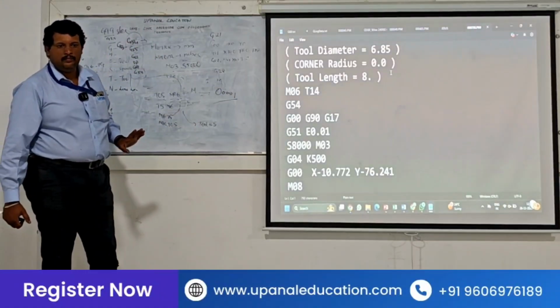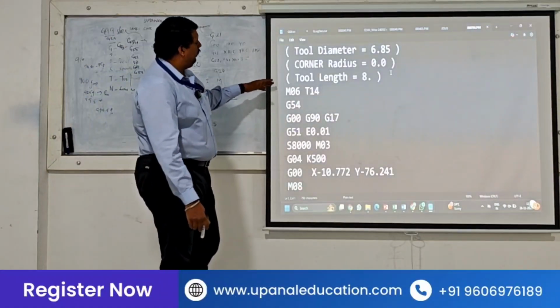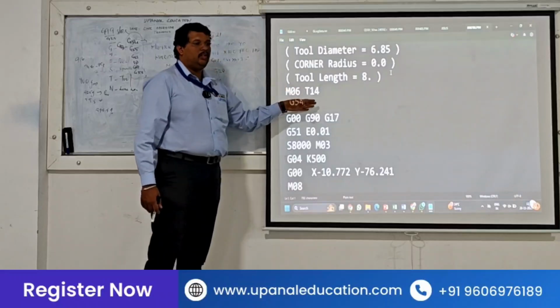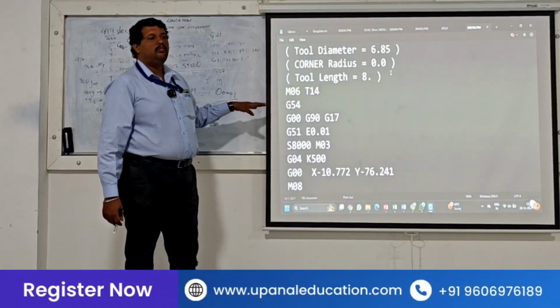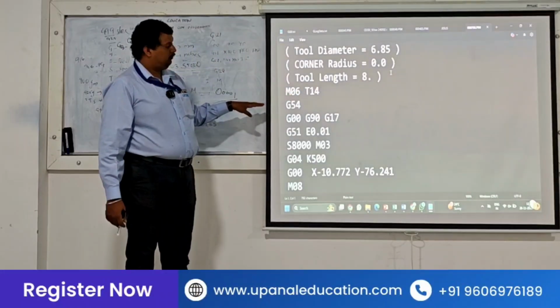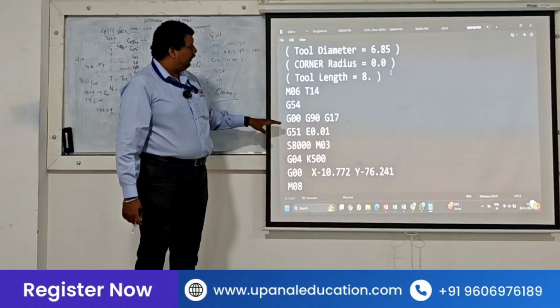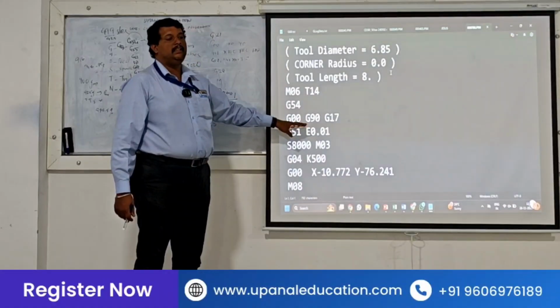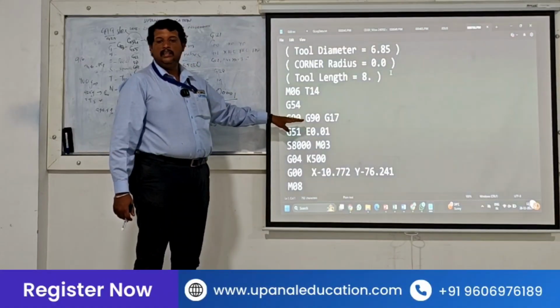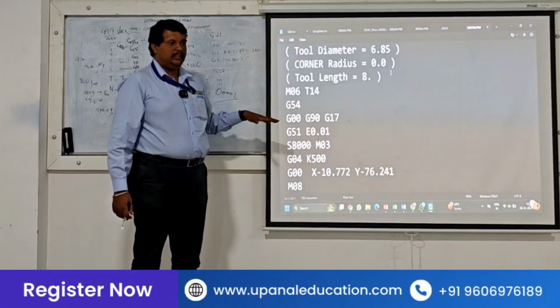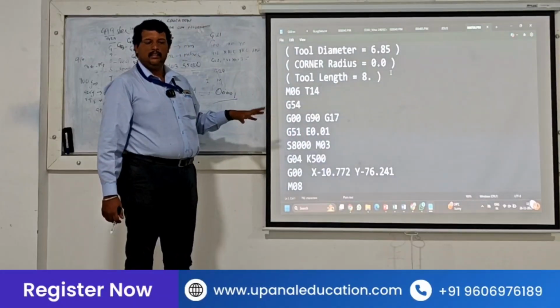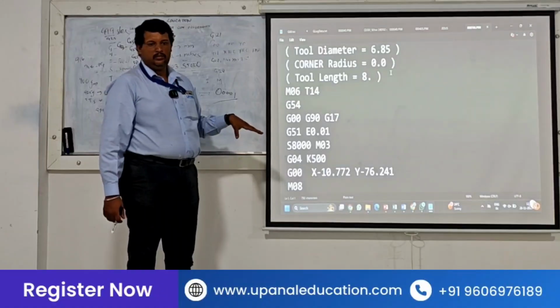Understood? Then we have M06 T14. I am calling the 14th tool. Then we have G90. We have the coordinate system, absolute and incremental. I will explain that later.